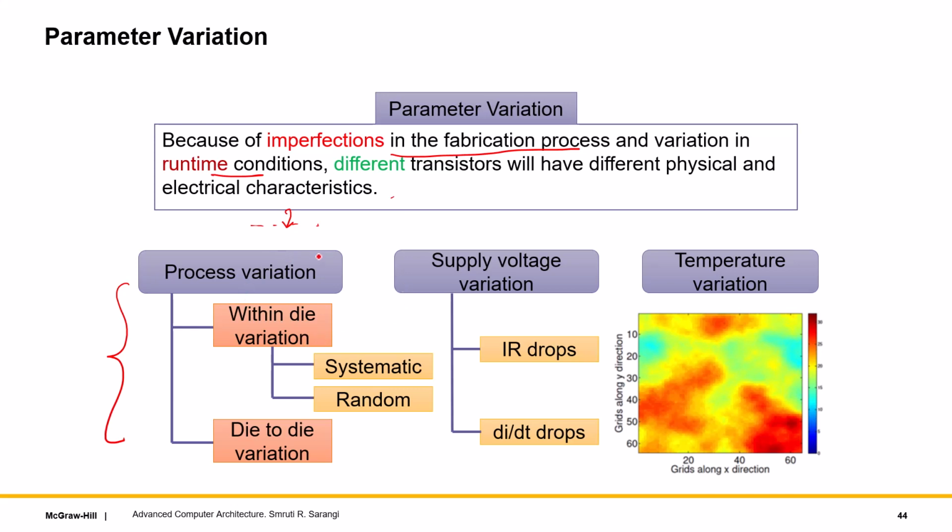So that will lead to some manufacturing-related process variation, which will vary, of course, die to die, different dies, different wafers, and within the die, within a single CPU, you will have some variation. You will have some variation even at a very small scale, like even in, let's say, 10 transistors. So you can broadly divide it into two parts, systematic and random, where systematic are basically these low frequency variations throughout the die, like a high region over here and a low region over there.